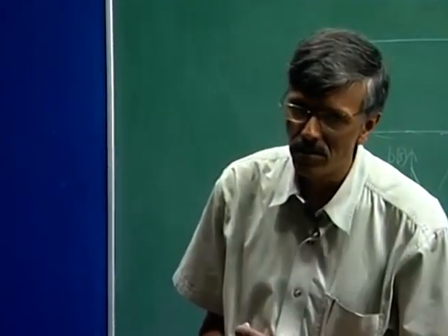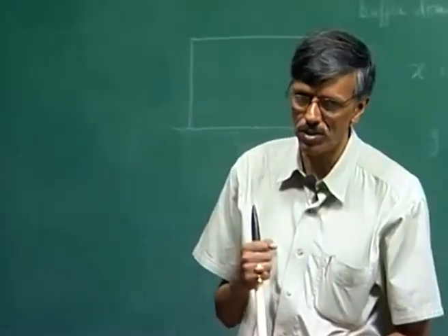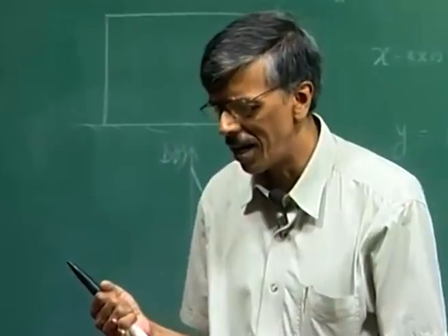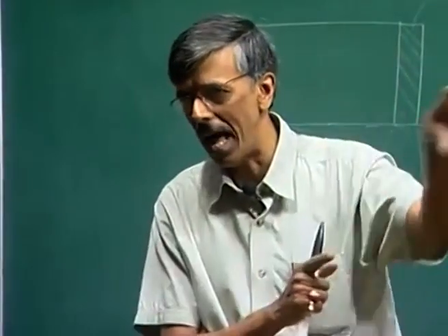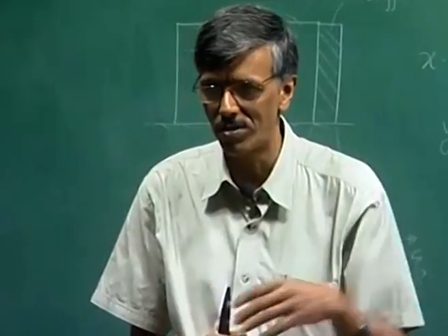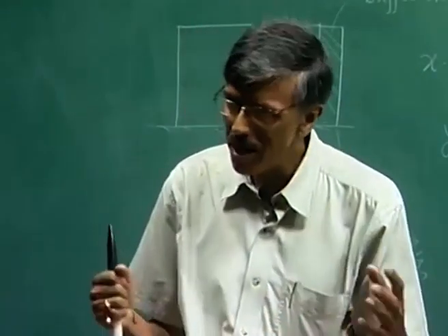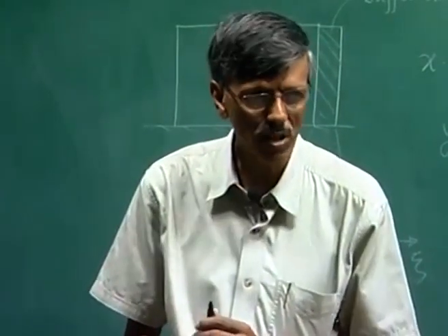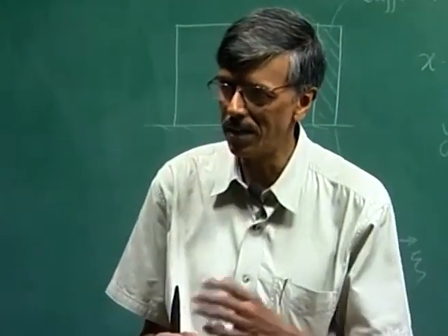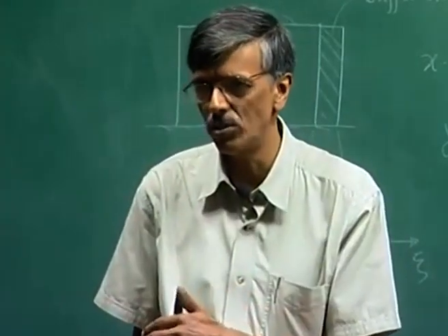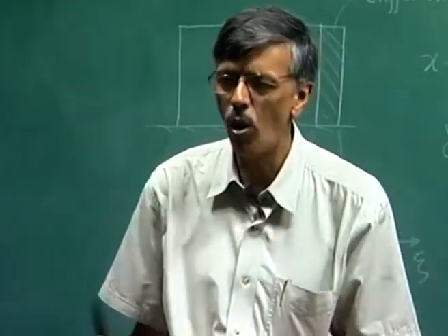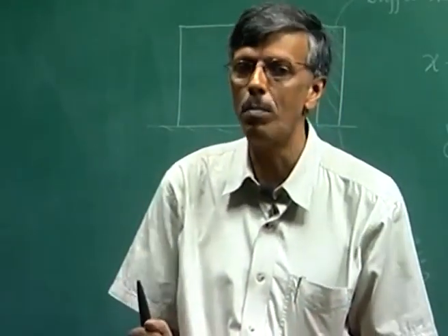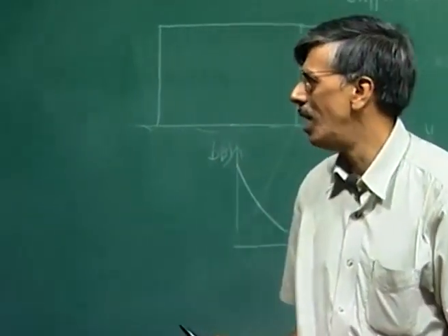He coined this term called bypass transition, and what he meant was that there are all these nice lab experiments where we demonstrate Tollmien-Schlichting waves, but there are many flow situations where Tollmien-Schlichting waves are not at all relevant, and they are undergoing transition due to some other mechanisms. So, all these other mechanisms taken together, he coined as the bypass mechanism.